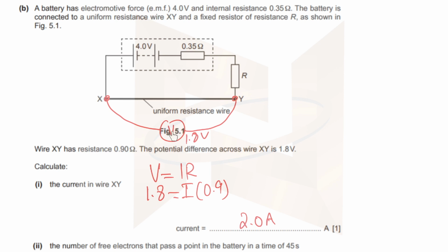Why? Where is this voltage? V = IR. The voltage and the resistance must have a relationship. Remember this. If you are using the EMF, which is 4, then you take the resistance of the whole circuit. Only when you're using the EMF. Let me write that down over here. EMF = I_total × R_total. Please refer to my electricity videos if you've forgotten this. It comes from V = IR. If instead of V you put EMF, now EMF is of the cell, and the cell is of the whole circuit, not a particular part. So if you're using EMF, you take the entire resistance of the circuit. But over here, they have not given you R, so I cannot use 4 by any means.